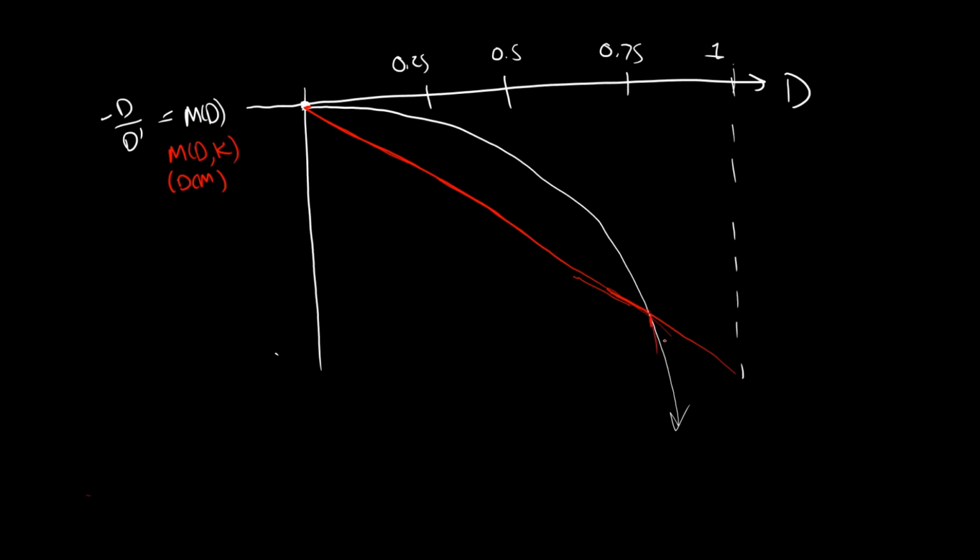And I should point out that the intersection of DCM and CCM is actually continuous, right? So when you transition from DCM to CCM, the conversion ratio will just pick up where you left off. It won't be smooth, right? There might be a cusp, but it will be continuous. So it's linear, right? And it has slope 1 over root k. And maybe I'll put a minus 1 over root k is the slope. So as L, TS, and R vary, the slope will also vary, right? Varies with k.